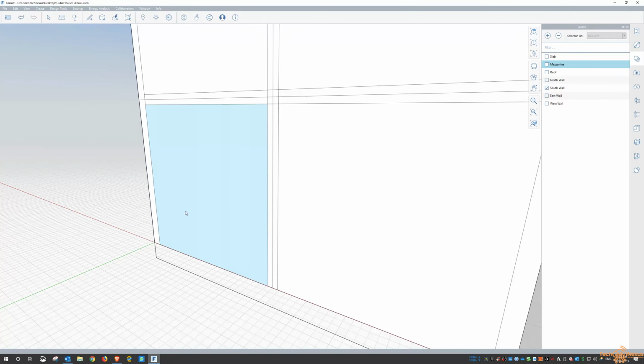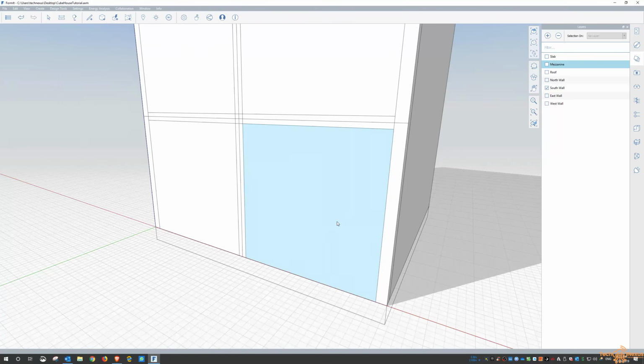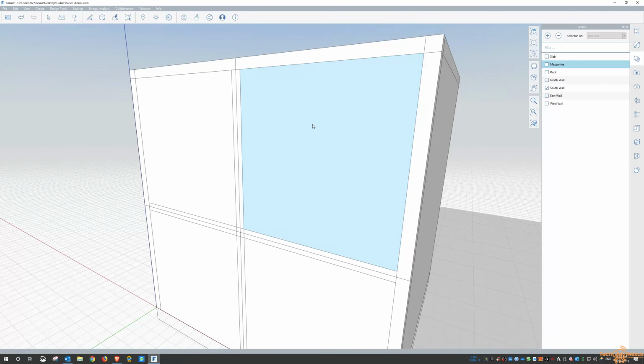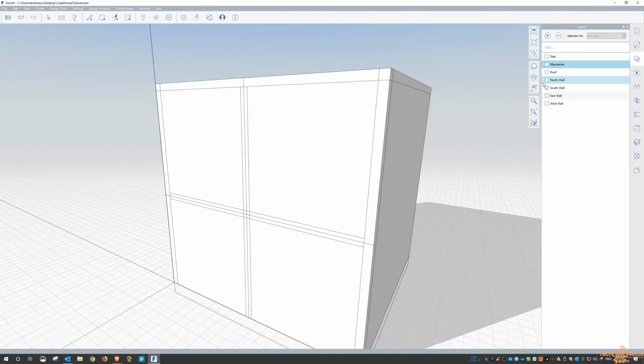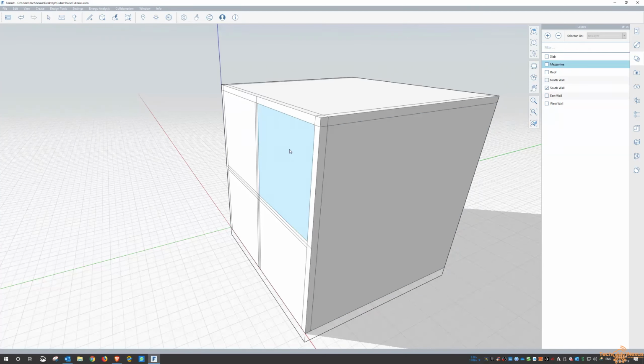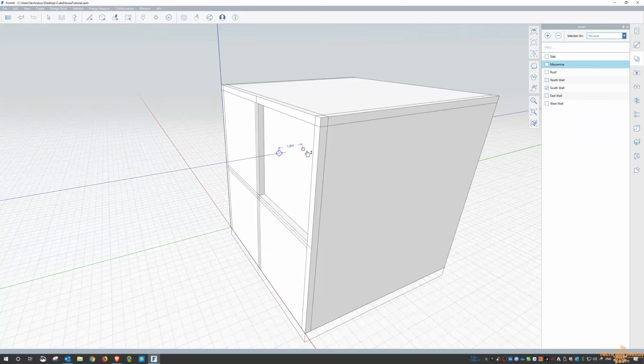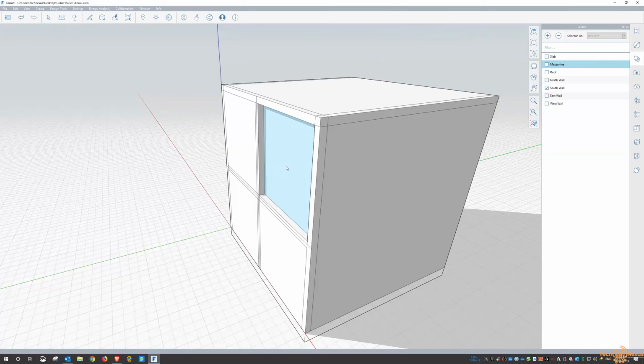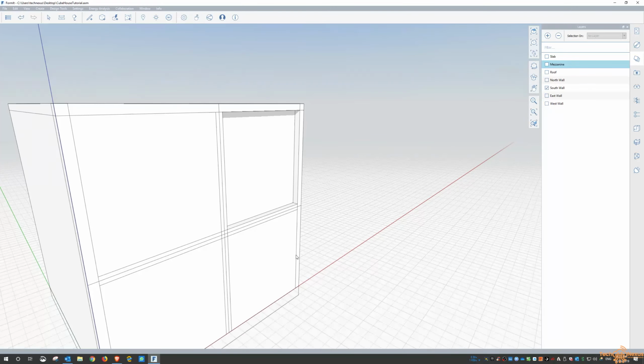Actually, no, let's make it nothing because it's going to be nice and flat on the floor there. And then that's going to have the roof, and then that's going to be the edge of the bricks. So from here, let's go through and then just do a push-pull on this. Okay, and then that should cover it.